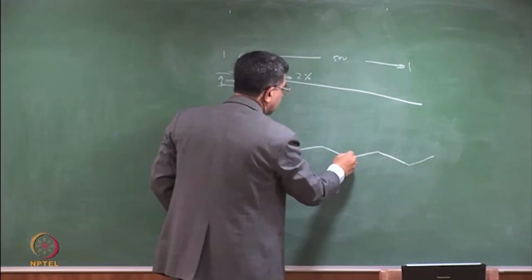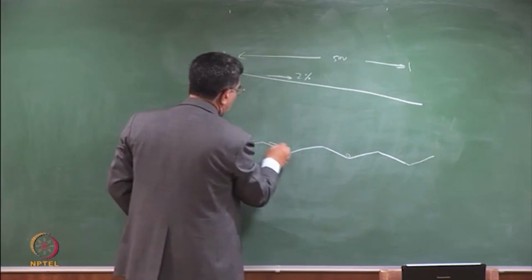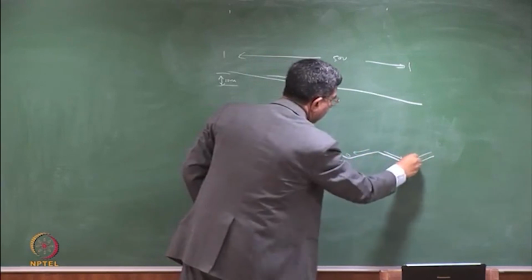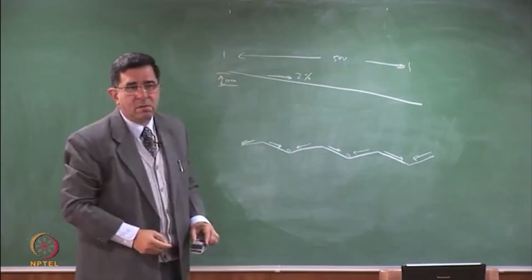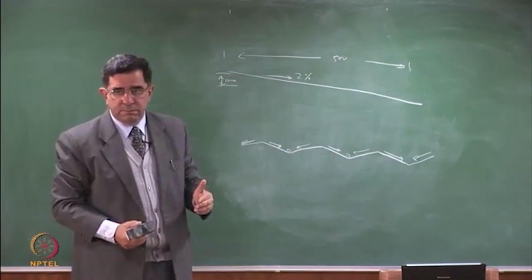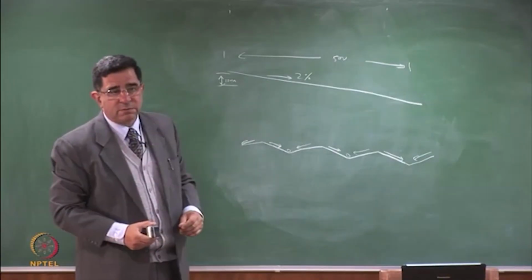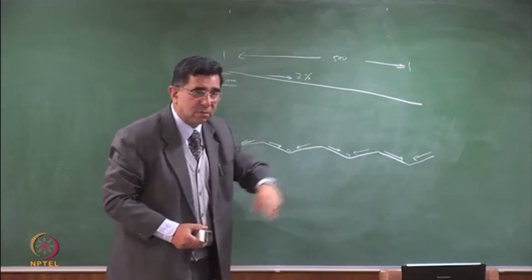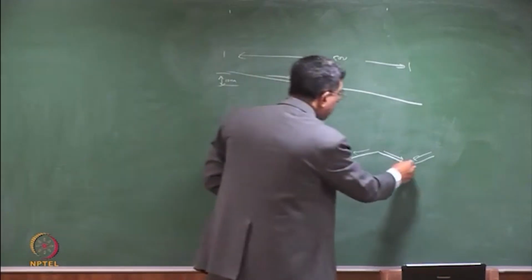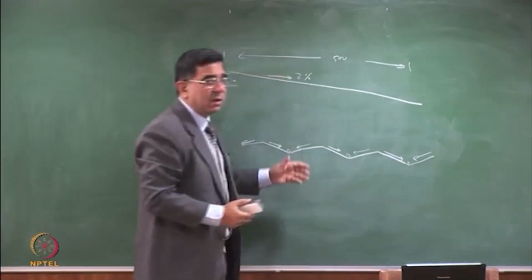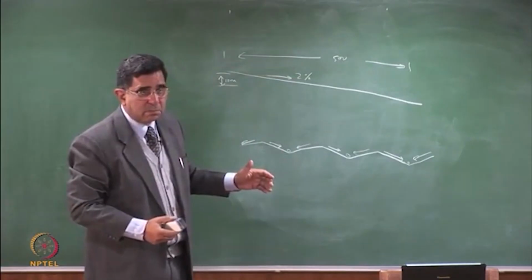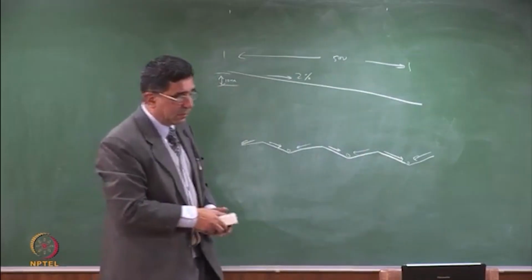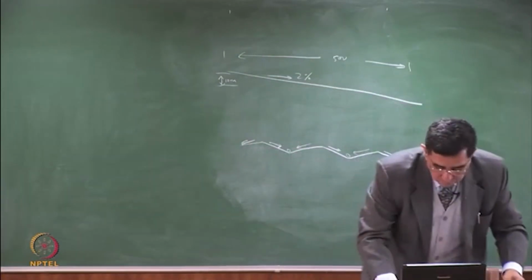With the drainage pipes, you make the leachate flow in short lengths. You have to keep the earthwork to a minimum. You don't want a very elevated difference in the facilities. And then in this perpendicular direction, you take out your leachate. Okay? This is sometimes called the accordion arrangement, but it goes like a corrugated base.